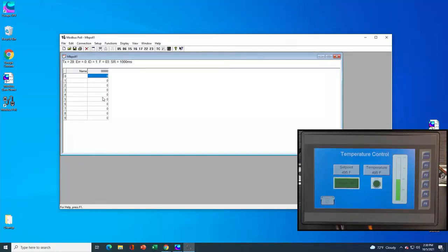You want to probably be able to monitor and even change the temperature set point. You want to be able to monitor the current process temperature. You probably want the ability to remotely, manually activate the heater if that's a function that you want to perform over Modbus. So that's the data we're after, but that data has to be mapped into Modbus register space before that can actually work. And I'm using variable-based programming. With variable-based programming, there is no automatic mapping to OCS register space, which means there's no automatic mapping to Modbus register space either. So that means we need to do that manually.